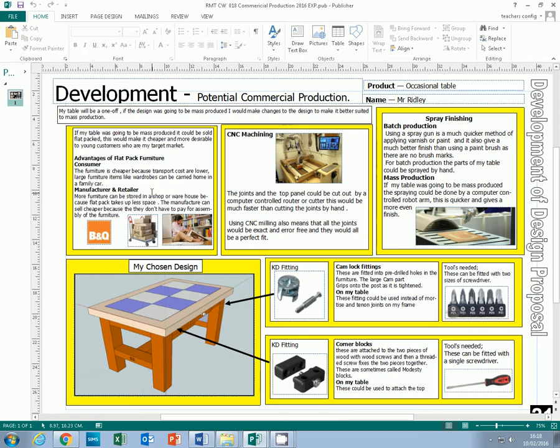We can also look at the environmental impact of it, and we know that transporting it, for example, if it's flat packed, it's much cheaper to transport, uses less fossil fuel. So that's flat pack. Now, if we are going to flat pack our table, which is our main consideration here, we would use KD or knockdown fittings. These are fittings that can be assembled by the user, by the person that buys the table.